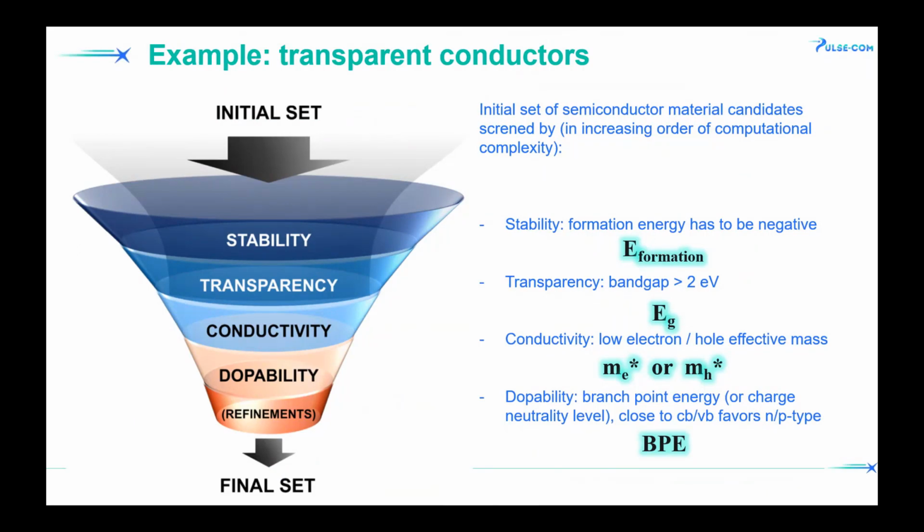it has been applied to transparent conductors. So you can have N-type transparent conductors, you can have P-type transparent conductors. The most prominent example is ITO, or indium tin oxide, which is the N-type layer that is used in electronics as the conductive layer. So a sort of mission that a large part of the community is to find the P-type transparent conductive oxide, which would hugely extend the range of applications.